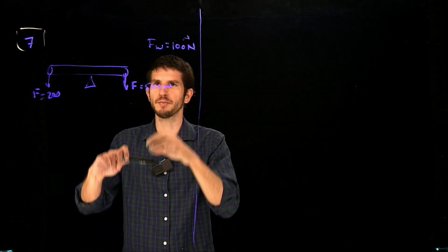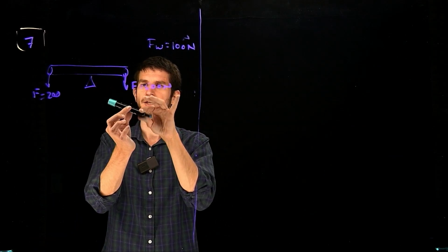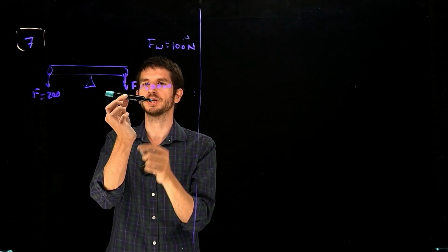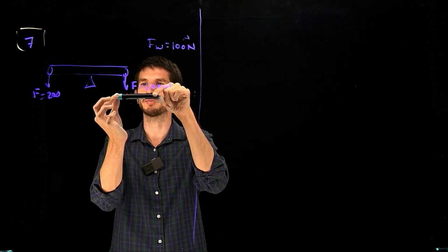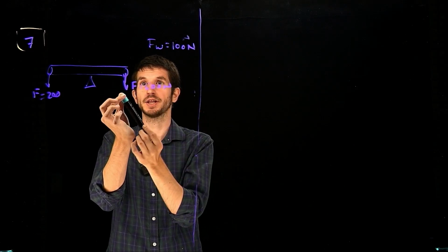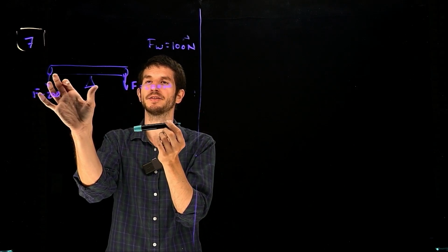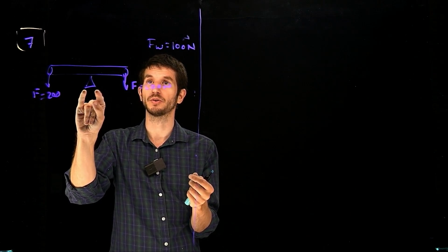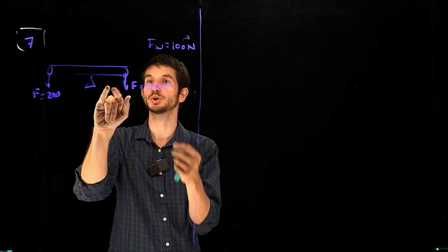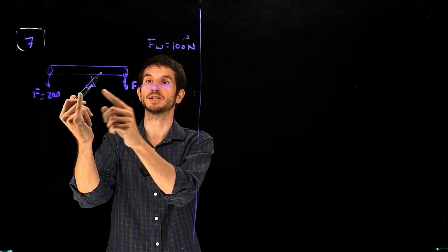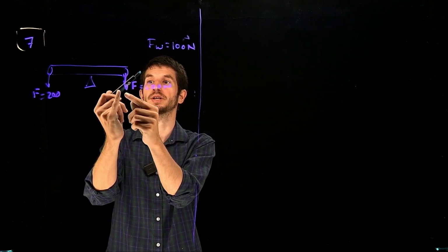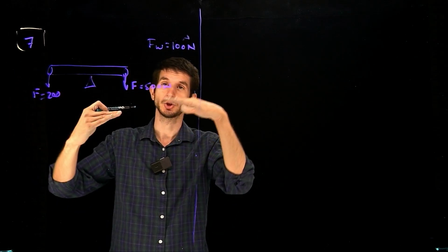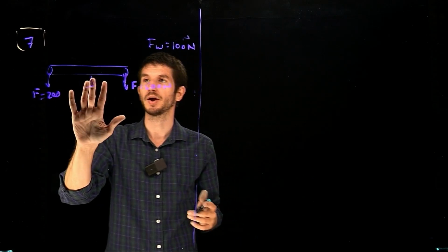So if I ask you, if I'm pulling from two sides, and remember we said, how is it easier to rotate this pencil, if I push like this from the middle or if I push like this from there? So it's much easier there. So then the higher the distance, the more torque. So where am I going to be placing the fulcrum is probably closer to the higher force, because this is multiplicative with the distance. So I want to reduce this. I reduce it by bringing it closer, which at the same time is increasing distance in here. So it's multiplying this.